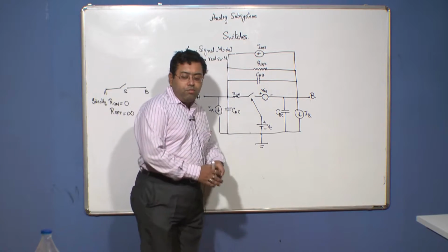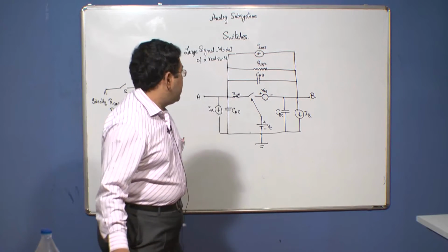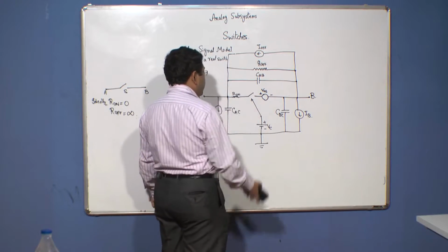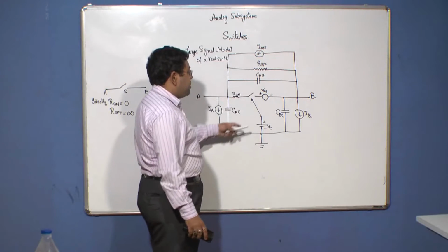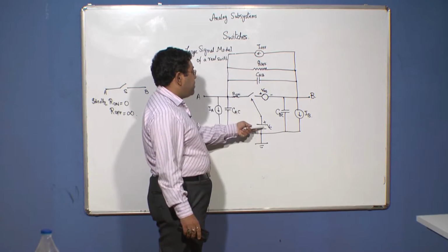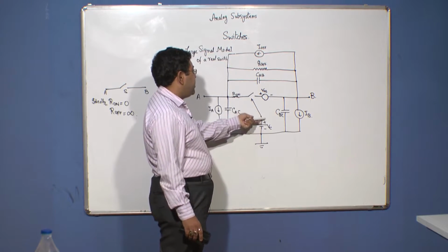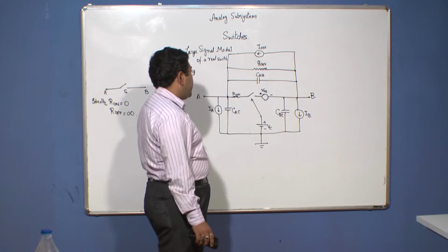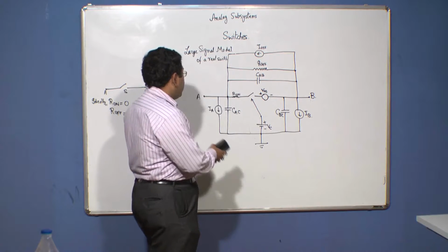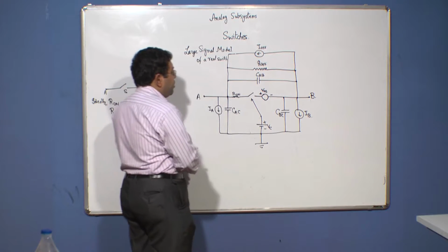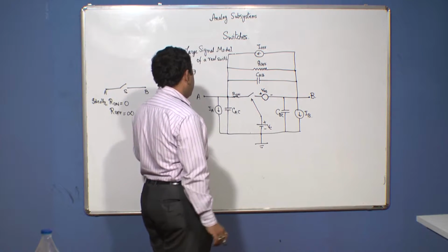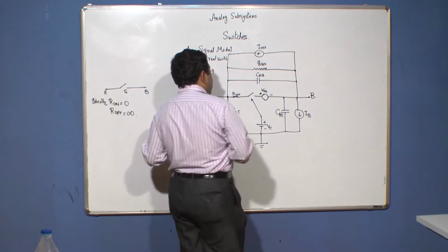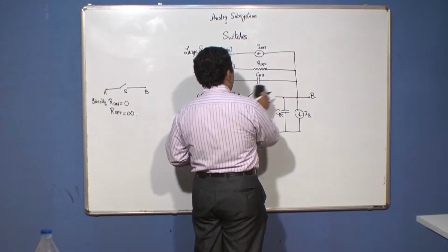Now, when it comes to a MOS transistor, the MOS switch basically represents a voltage controlled switch like this. This is a voltage controlled switch. Why? Because you are using this control voltage Vc to turn on or turn off the switch between nodes A and B. Now, for this voltage controlled switch, when implemented using a MOS transistor, this R on refers to the channel resistance. On the other hand, we do not find this offset voltage.